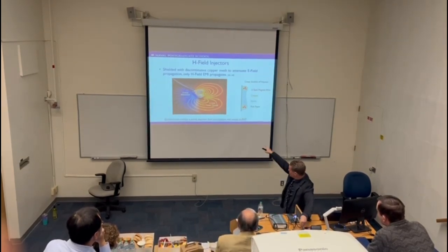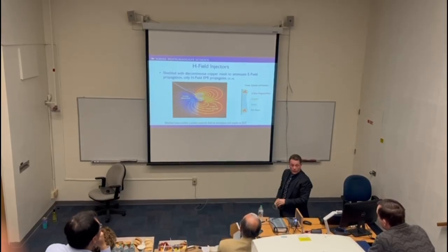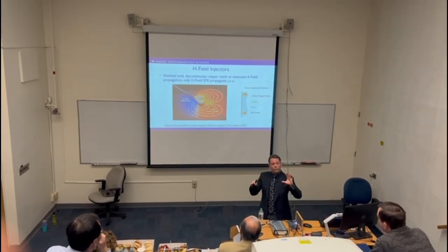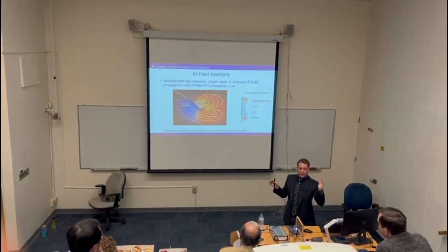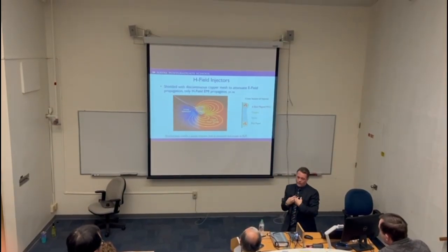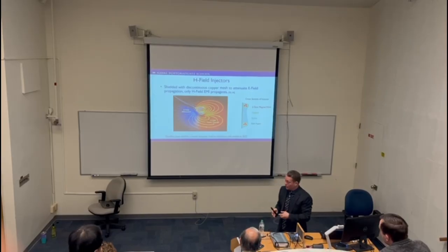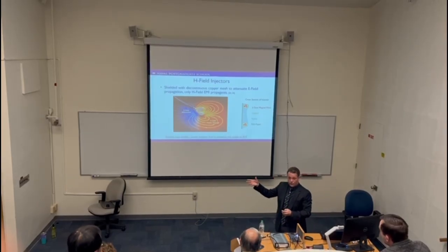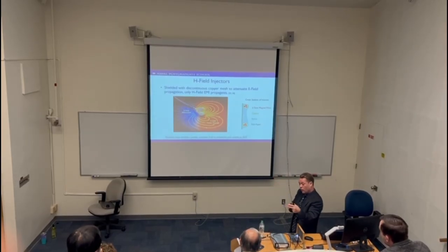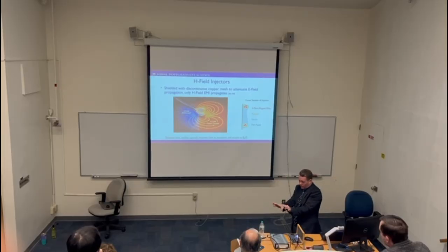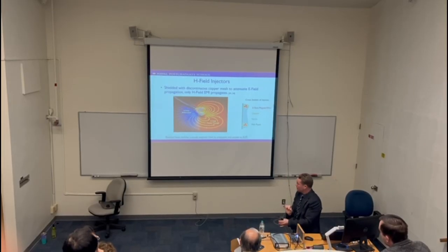This shield has the effect of essentially decoupling H field from E field. I can tone down, because again, I want to inject a very specific type of EMI. If I want to inject more differential mode type coupling, I'm going to inject my H field. If I want common mode, I'm going to try and go for E field. But I want to attribute it all to as much differential mode as possible and know that it's from H field at the frequency that I want.